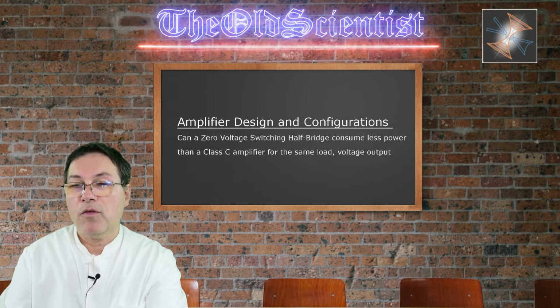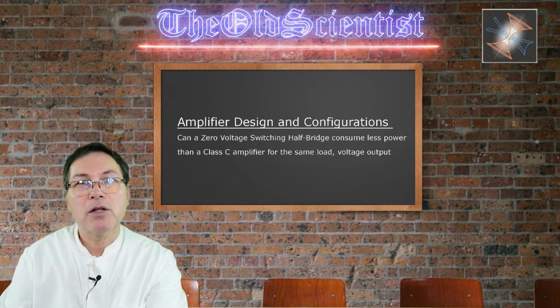The power required should logically be the same. However, there are losses from the single person waiting until it can push again. These losses are cut by half for two people who do not need to wait. In general, we can say we have less losses with a half-bridge, but for that to take effect, the design must be very efficient. Compared to bootstrap technology, my ZVS design does not require a very tight component selection for DC bias and bootstrap capacitor, which operates only at one frequency, one voltage and one current level. Now let us have a look at the demonstration table and the PCB boards I use for my test today.